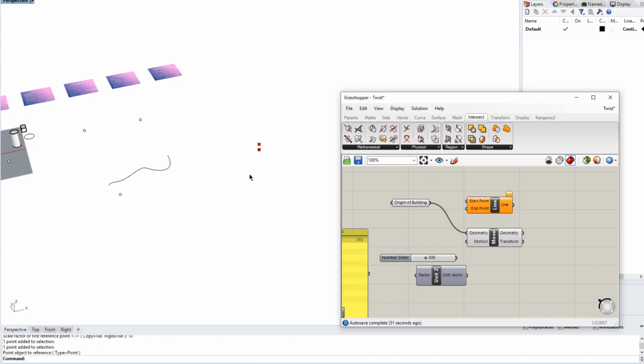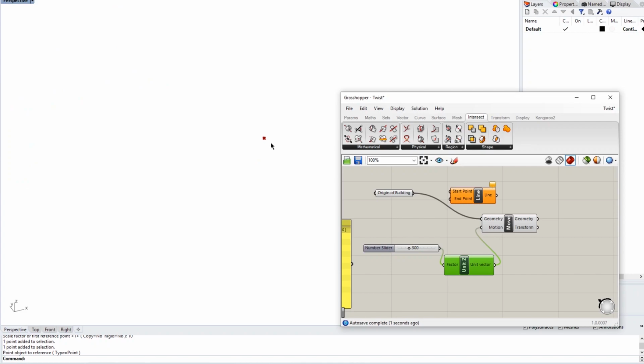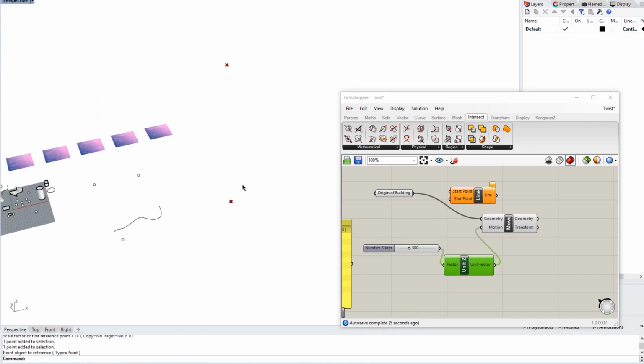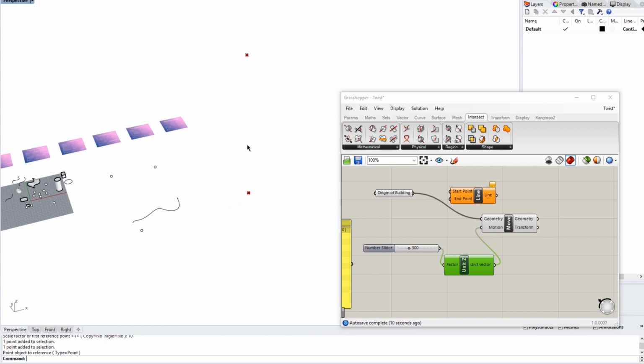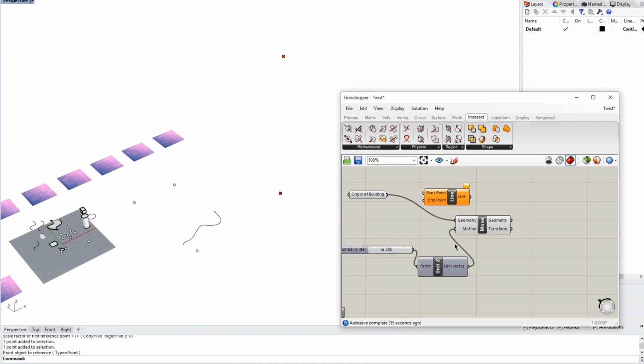If we would like to have a 3D model, we will need to follow the 3D coordinates. So in this case, we are using the Z vector. I would like to move my point 300 units in the Z direction. Oh, is it too little? Oh, it's here. Alright, this is what I want. 300 units in the Z direction. Let me orbit a bit just to see the difference.